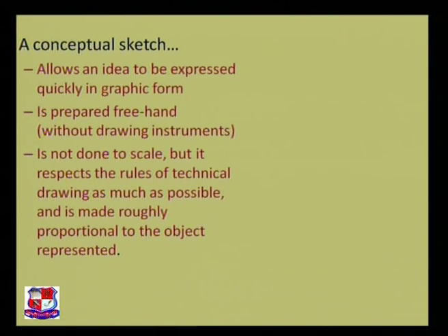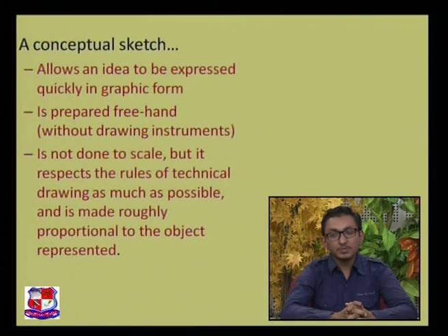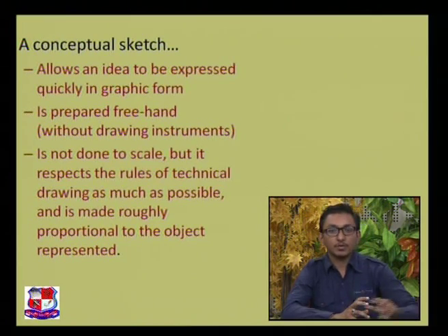A conceptual sketch allows an idea to be expressed quickly in graphic form. It is prepared freehand without any sort of drawing instrument. It is not done to scale, but it respects all the rules of technical drawing, such as various parameters, and it is made roughly proportional to the object represented. I am making a rough drawing, but it should also represent the final object. It should look like the final product, but it should not be drawn using drawing instruments.